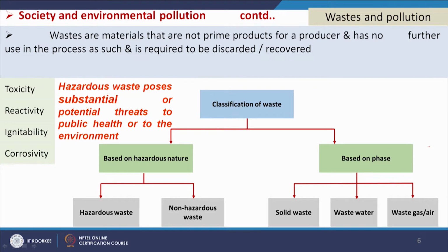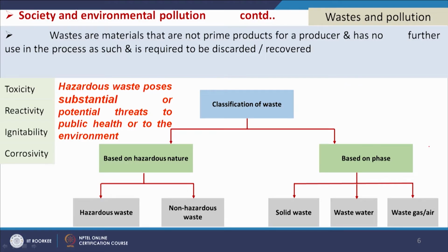If we classify the waste, we can classify it based on hazardous and non-hazardous nature, and also based on phase. We know that hazardous wastes are pollutants having certain properties like toxicity, reactivity, ignitability, corrosivity, or any one of these or any combination or all of them. Those wastes or pollutants are hazardous pollutants or hazardous wastes, and non-hazardous ones do not have those characteristics. And based on the phase, the waste or pollutants can be in solid, wastewater or in gas phase also.